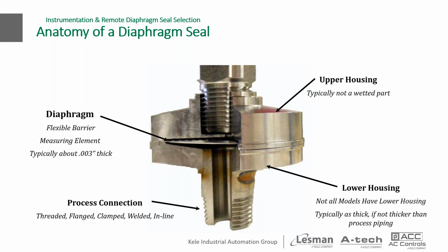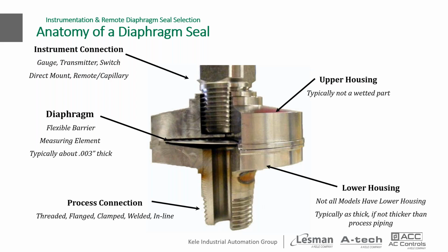It usually adds about 2 weeks if you want carbon steel that's nickel plated, and that's of course going to slow down delivery to you. And finally, we have the instrument connection. Again, 1/4 inch or 1/2 inch MPT female threaded connections are very common, but as I said before, whenever possible, we would much rather supply you a welded connection. When we do that, there's obviously less opportunity for the assembly to fail from fill fluid leakage if you have a welded connection.